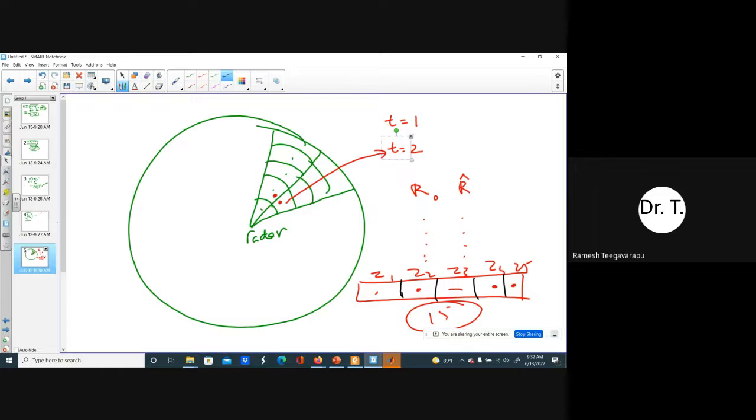Now, we can do this for a longer period of time, where we have all the rain gauge values and then radar values. Then we go through the whole idea of bias correction. Because, as I have indicated, sometimes because of instrumental errors or systematic errors, the radar is on average overestimating or underestimating the rainfall. That can happen over the entire region, or over a particular small area. So the bias corrections can be applied locally or globally.